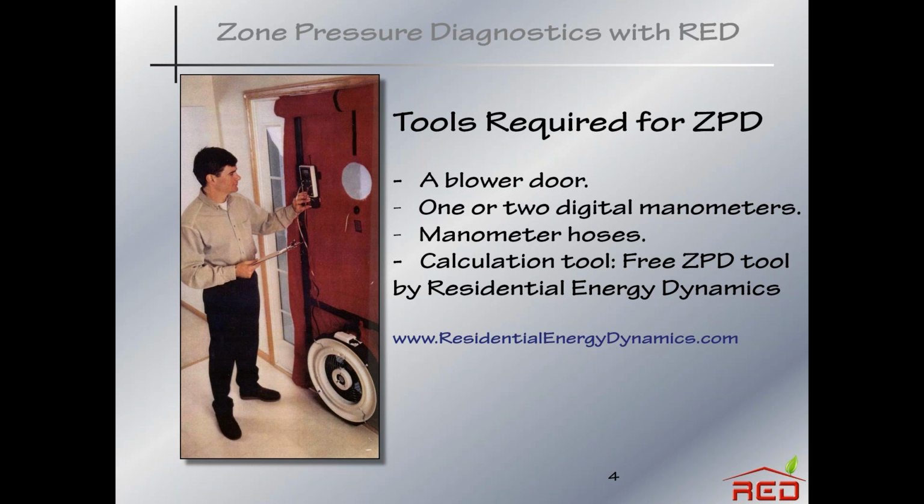I, for example, have an old Energy Conservatory DG3, and I also have a DG700. I often use the DG3 when I'm doing zone pressure diagnostics. Otherwise, I never use it. It can shortcut things a little bit and help you stay better organized out in the field when you're doing ZPD. You need manometer hoses.